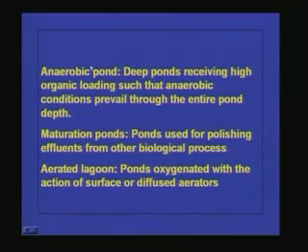Aerated lagoons can also be classified into two categories: aerobic lagoons and facultative lagoons. In aerobic lagoons, what happens? The complete system is in aerobic condition, and the entire suspended solids present in the system will be in suspension. That means the aeration will be so rigorous that all the suspended particles, even whatever has already settled, will come into suspension, and definitely the treatment will be more efficient.